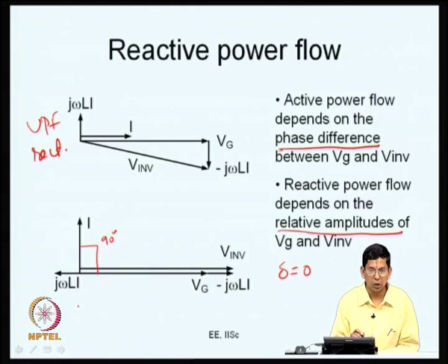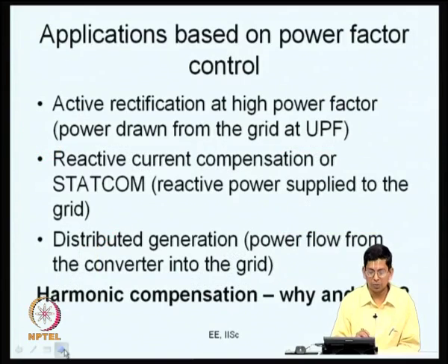If you want, you can also draw reactive power from the mains, but that is not what you normally want to do. You want to supply reactive power to the mains, so that the overall power factor of a particular facility is improved by such equipment, and this is what you call reactive current compensation.